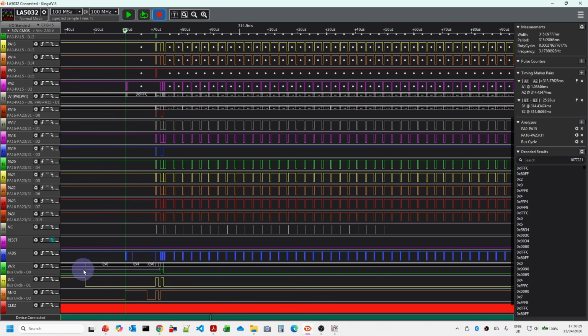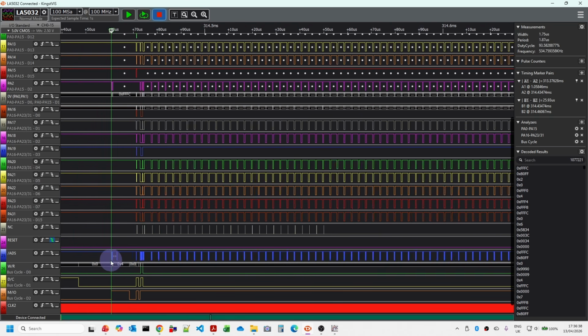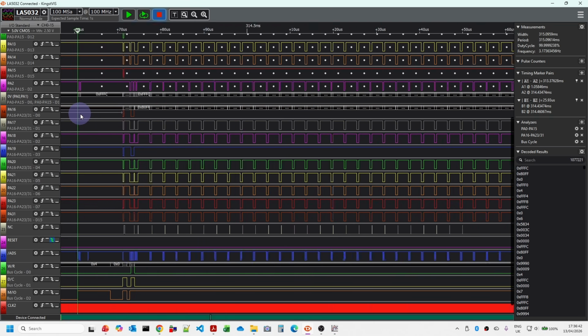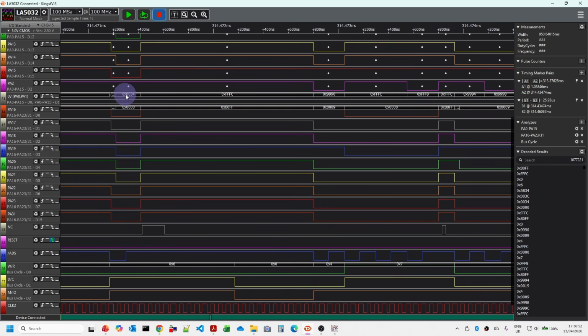So after a period of time when the reset ends, we do actually have a code 0, which is interrupt acknowledge, and then 04 is actually reading code. So at this point in time, it's reading code, but then there's a bit of a gap. And when we see our next address strobe here, you can see that we're not actually executing the next instruction. We're actually reading from 000, so this is in the bottom 64K of RAM, and we're actually reading from 34 hexadecimal.